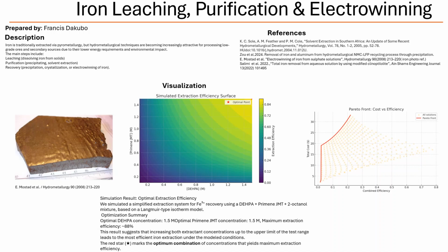Exactly. So they define linguistic variables for the concentrations, like very low, little low, stable, and so on. And they do the same for the trends, negative big, positive small, things like that. Then they have a set of fuzzy rules that link those inputs to an overall evaluation grade for the process. So it's a way to capture expert knowledge about what makes a good process, even when things aren't perfectly precise. And then they can use this fuzzy system to pick the best solution from that Pareto set.